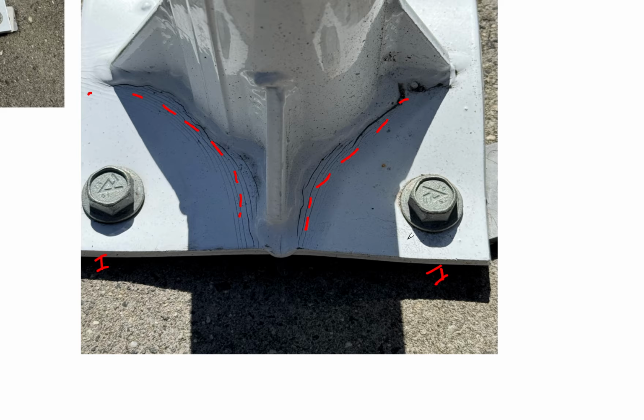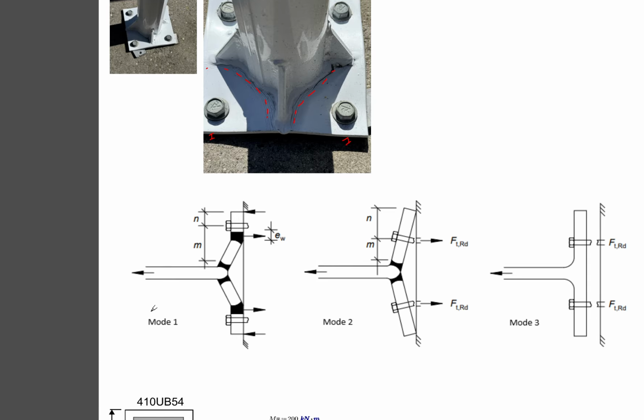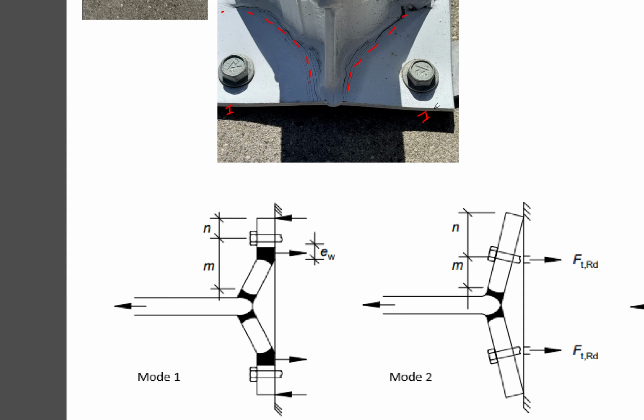So that means the bolt gets stretched, elongated a little bit. This is the typical mode 2 failure of the yield lines. But for mode 1, obviously you don't get this separation at the bolt. Your bolt is still secured to the pavement, to the concrete, or to the boundary conditions, whatever you might have. You only get the flange yielding. That's your mode 1. And mode 2 is a combination of the flange yielding plus your bolt elongation. So this is a combination of the two.